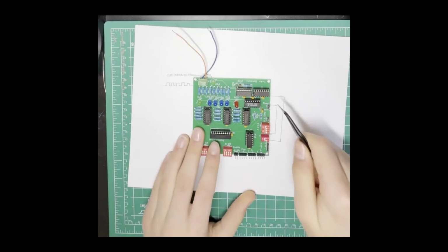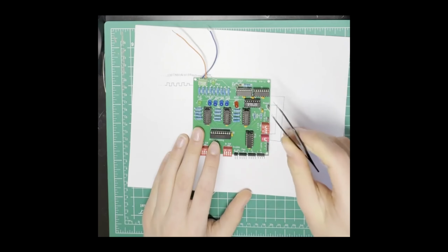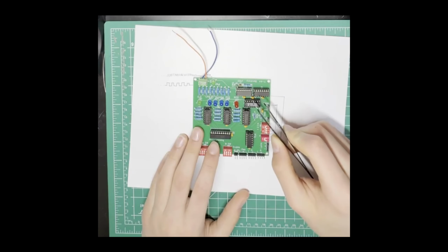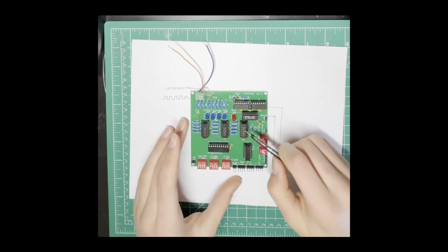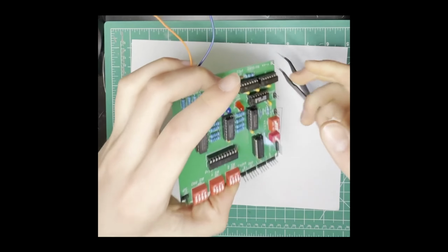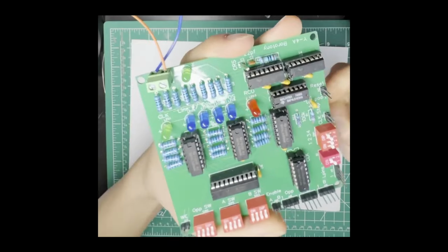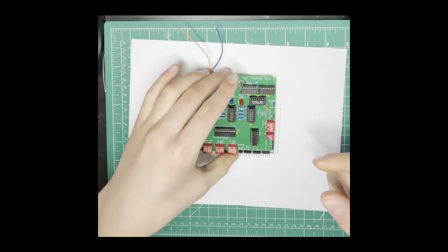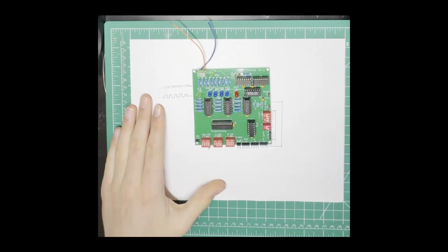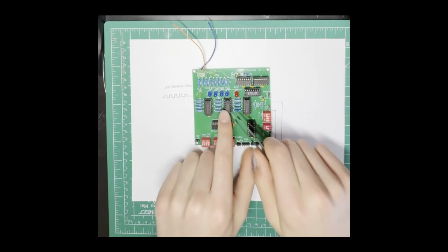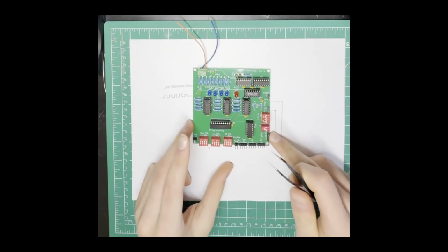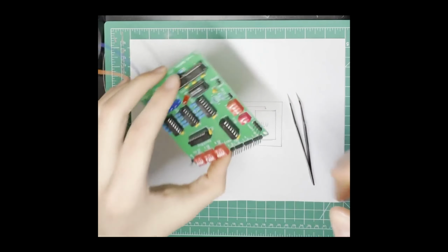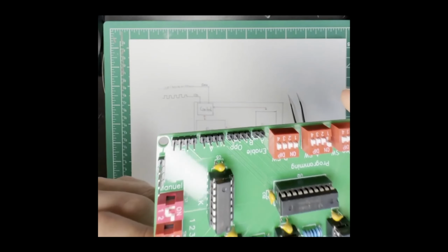This part up here is the clock generator. And so this is just binary counters, and this is also a binary counter. And so this feeds a usable 4-bit data input to the RAM. And now, if you notice here, we actually have 3 RAMs. We have this one, and this one. And that is for my 3 parameters for my instructions. So we have our opcode RAM, our A RAM, and our B RAM. Now all 3 of these feed into the CPU via these male header pins right here.